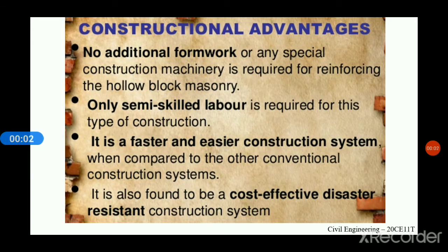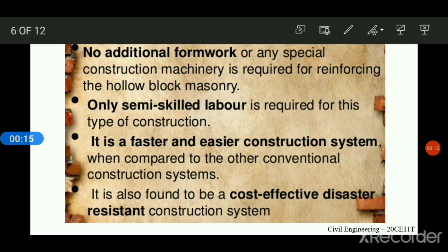So what are all the construction advantages? No additional formwork is required, and no special construction machinery is required for erecting hollow block masonry.